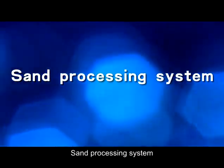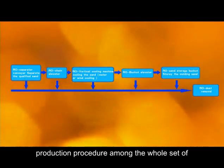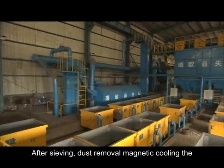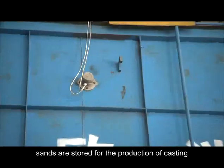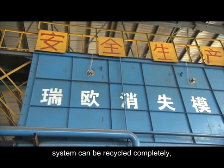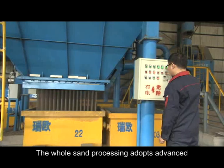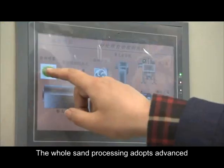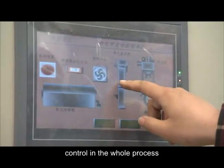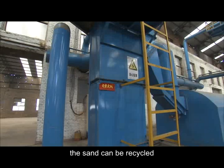Sand processing system. The sand processing system is a very important production procedure among the whole set of lost foam casting equipment. After sieving, dust removal, magnetic separation and cooling, the sands are stored for the production of casting. The molding sands processed by the sand processing system can be recycled completely, reducing the investment of production. The whole sand processing adopts advanced PLC control and is equipped with sand temperature control in the whole process. After sieving, dust removal and cooling, the sand can be recycled.